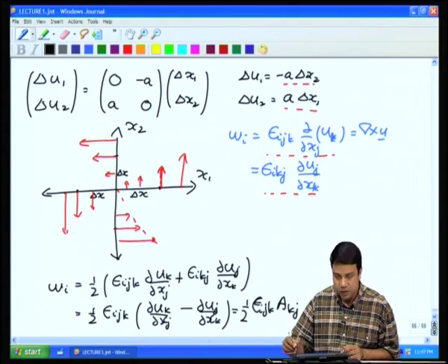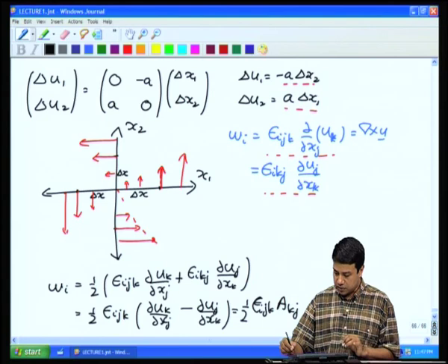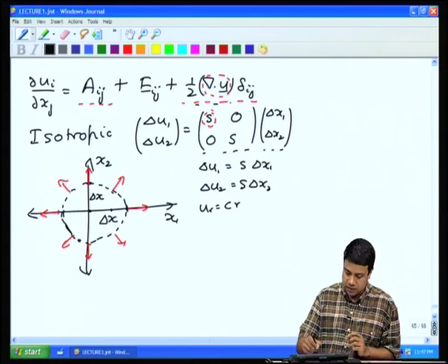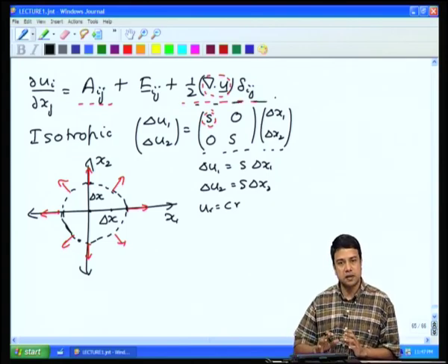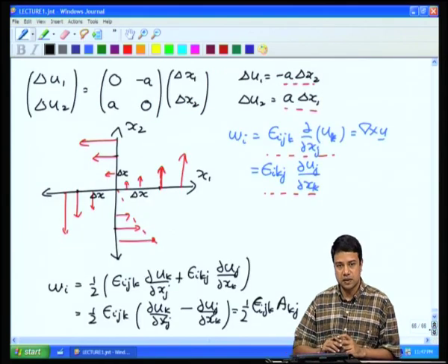That is the second part. First, isotropic, which we just did here, radially outward motion. Out of these three, this is the isotropic part. It represents radially outward or inward flow. It is proportional to the divergence of the velocity. Second is the antisymmetric part of the rate of deformation tensor.